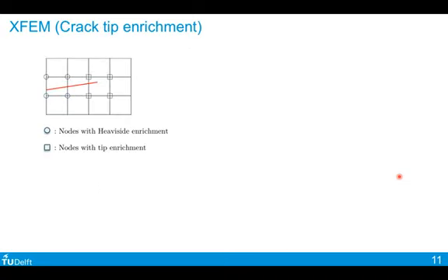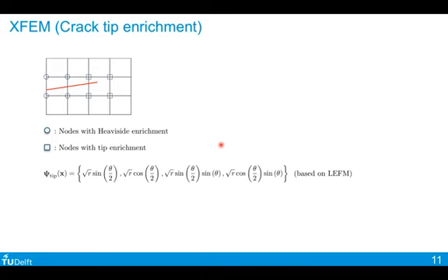And in X-FEM, we also have a second type of enrichment, which is called tip enrichment. This is more relevant to linear elastic fracture mechanics and for isotropic materials. In linear elastic fracture mechanics, for isotropic materials, we have an analytical expression for the displacement fields near the crack tip.